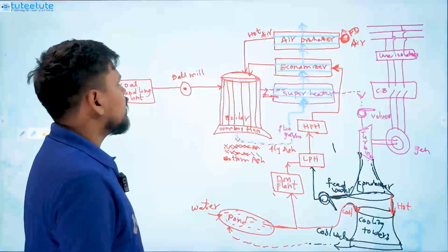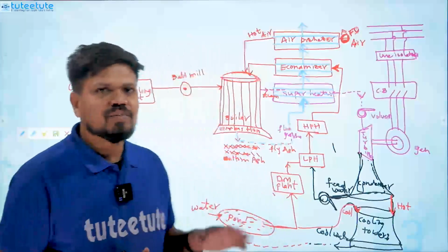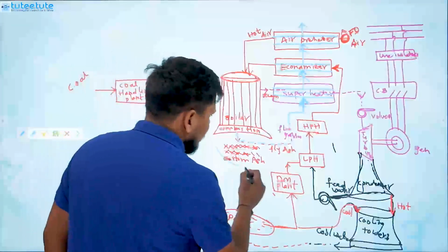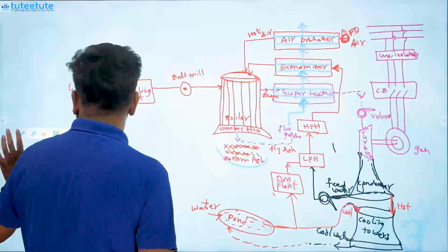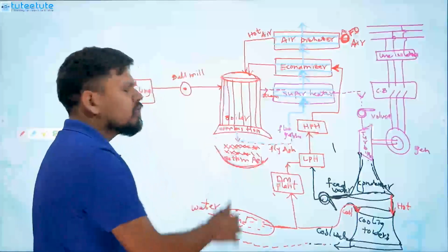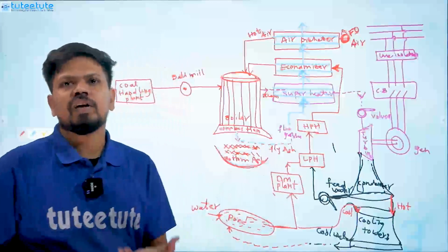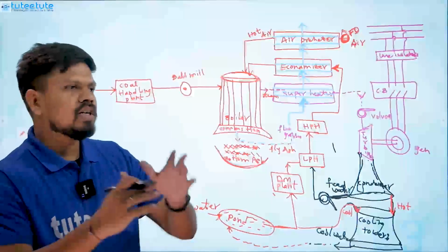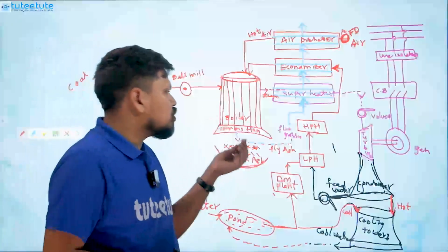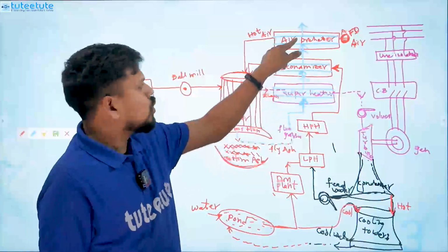Understood, right? So now these flue gases are very dangerous. You can understand that, right? The outcome of this boiler is coming from the ash material. Some of the ash content is very heavy. That heavy ash will come at the bottom of the boiler, and the fly ash means that which can fly, very less weight. Generally it has to go outside, into the atmosphere. So what we will do is use that heat to heat the steam, to heat the water, to heat the air.